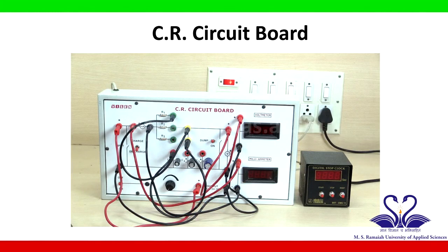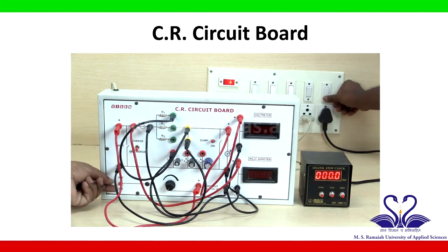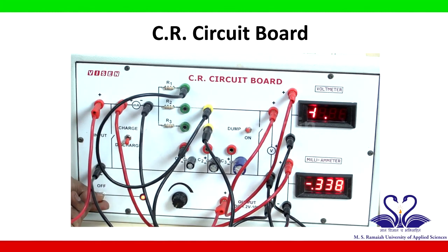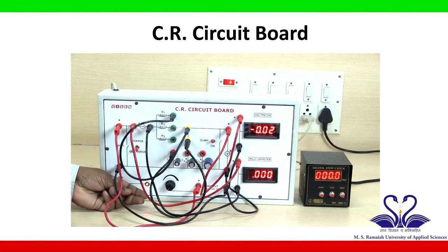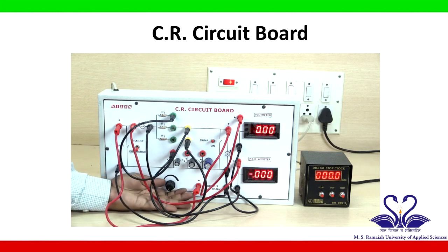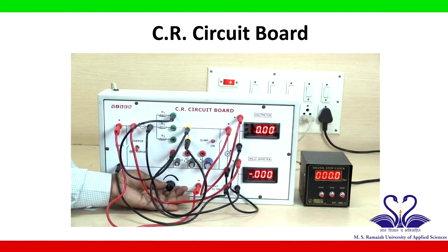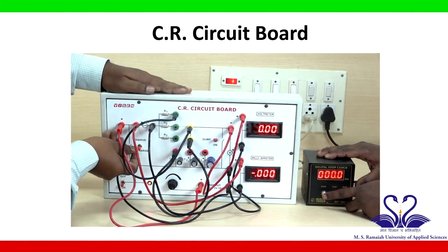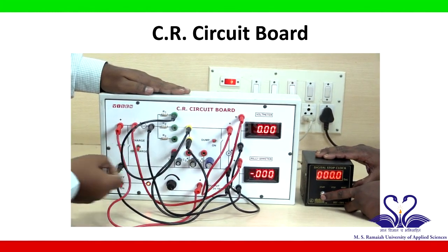Now let us perform the experiment. Switch on the apparatus, switch on the CR circuit board power supply, and before performing the experiment we need to turn the input voltage knob to maximum. Then simultaneously switch on the charging and stopwatch.